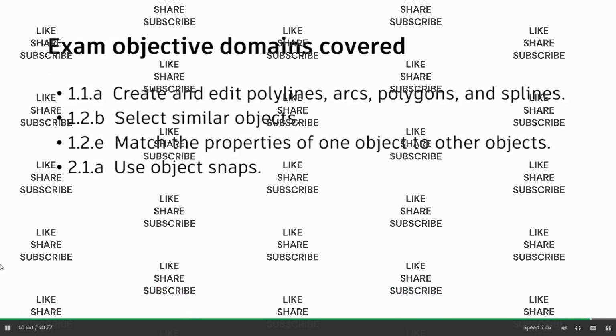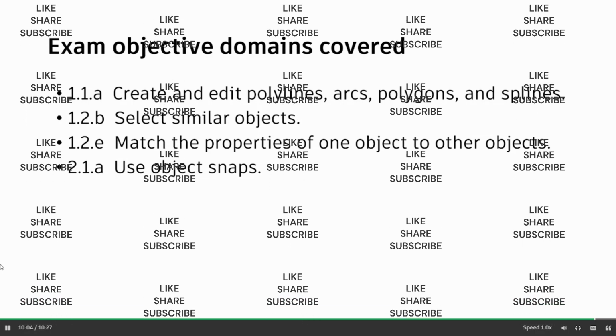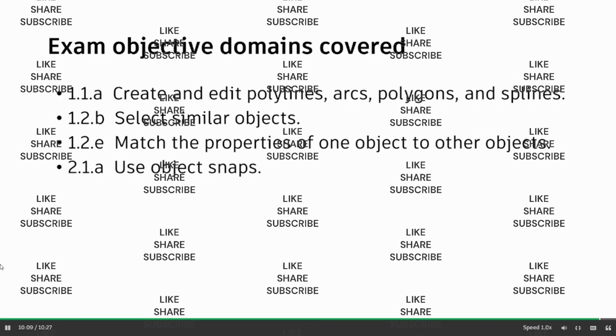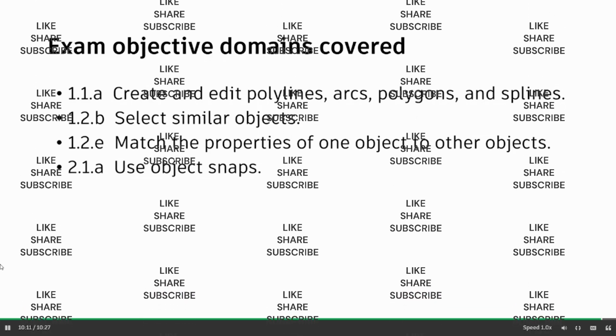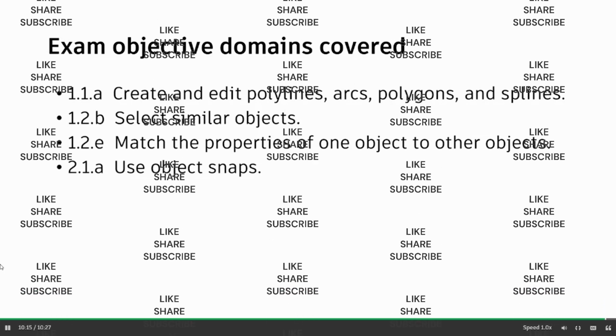We've reviewed different methods to create and modify polylines. We used Polyline Edit to convert lines to polylines. We used Match Properties to ensure that our polylines used the same width. And we used the Boundary command to create a polyline outline of our area.